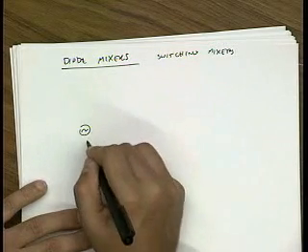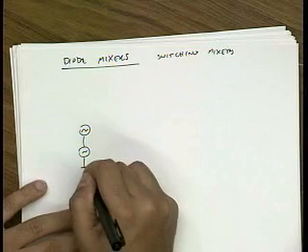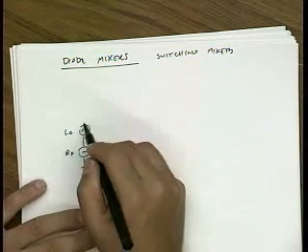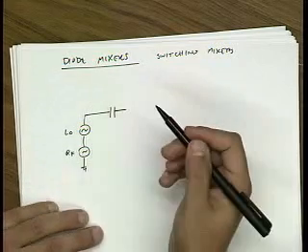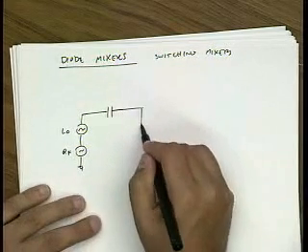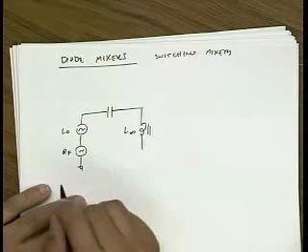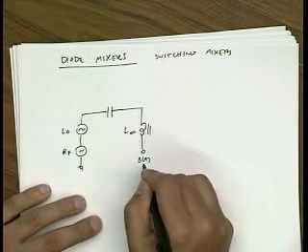Let me draw a very simple circuit, kind of an imaginary circuit. Let's say I could somehow put my RF and LO in series, for instance through a transformer winding. And let me bias up so this is a choke, let's say infinite inductance.